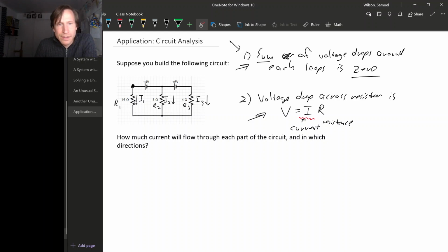The voltage drop here is, right, Ohm's law says it's the current times the resistance: I1 times R1. Okay, and then there are no resistors here, so no voltage drop along this wire. The next thing we hit is this middle resistor, but we're going backwards compared to the direction of positive current flow, so we need a minus sign. So minus I2 R2.